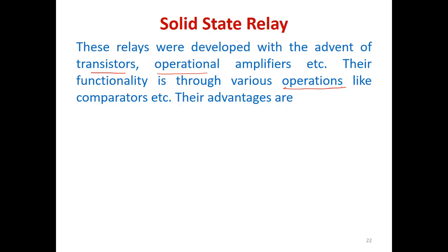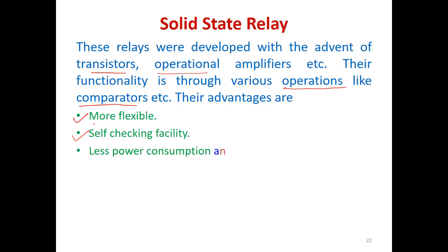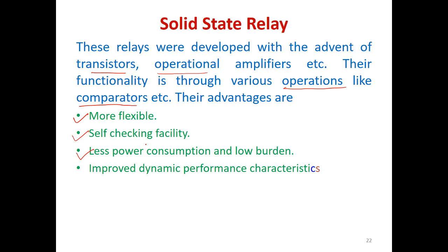So basically these relays were designed using comparators, and their main advantages are that they are more flexible, and there is a self-checking facility, where it can check whether there is some fault inside the relay itself, and less power consumption and low burden.